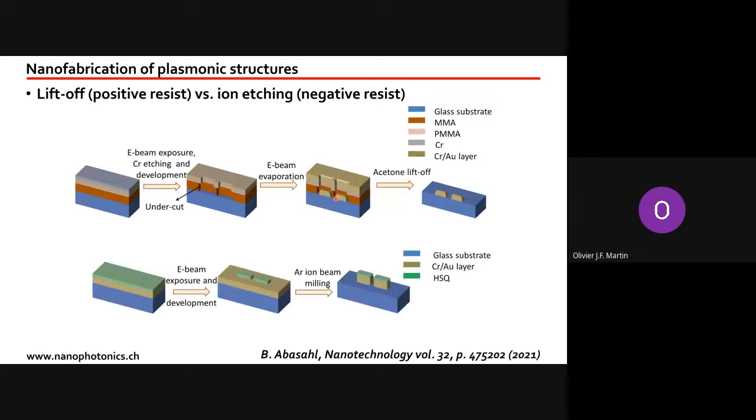The other technique is based on using a so-called negative photoresist. And for that technique, we start by depositing metal like gold. We deposit gold on the substrate, we put the photoresist on top, we write the same structures, but now because the photoresist is negative, instead of exposing the structure where the e-beam has written, it will leave the photoresist, which is going to become very hard and stay where we want to define our structures.